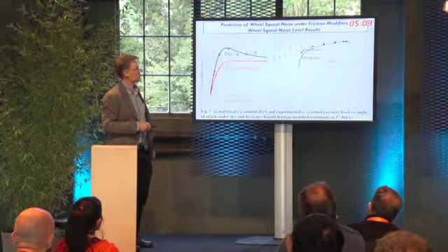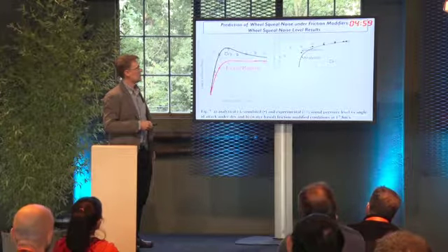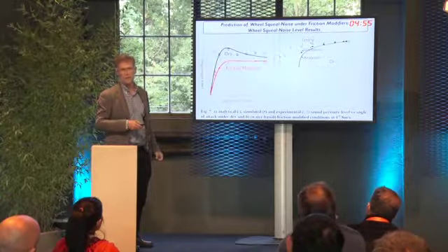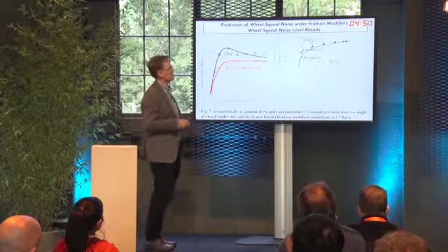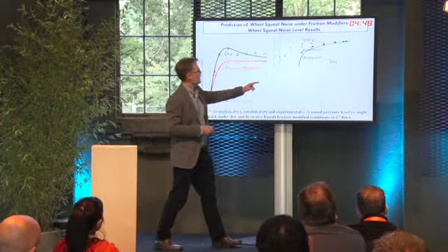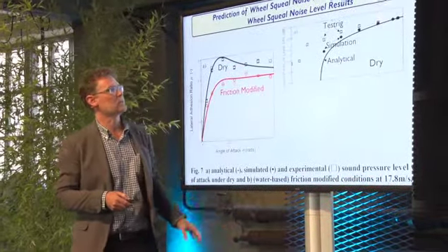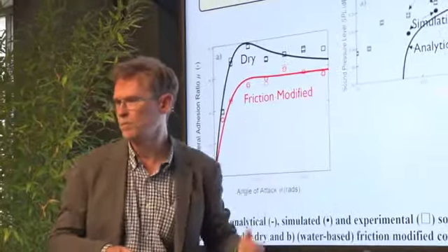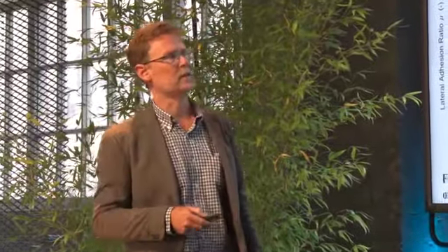Our simulation, which uses a more accurate creep curve, is reasonably close, and our test rig measurement results show a fairly good trend with angle of attack. You'll note we're overshooting at these low angle of attacks where typically squeal is not occurring, and it's likely that we're measuring other sources of noise there.